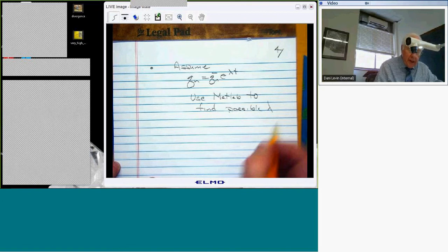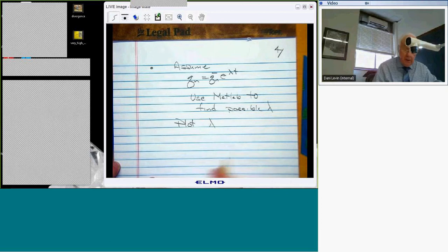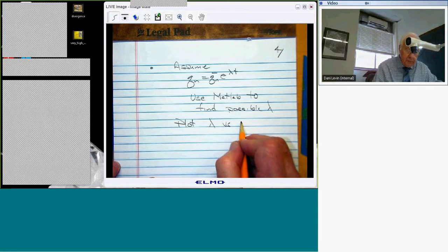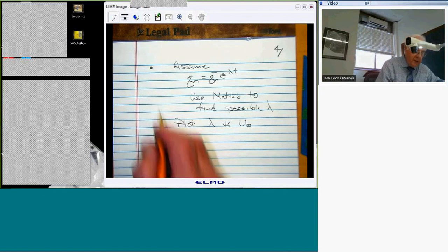And you'll want to plot lambda versus some parameter like u infinity. For a given altitude, you can pick sea level if you like. That'll give you rho sub infinity, a sub infinity, and then you can vary u infinity and see how fast this structure has to fly before it flutters. Okay, you can do that. So that's alternate one.